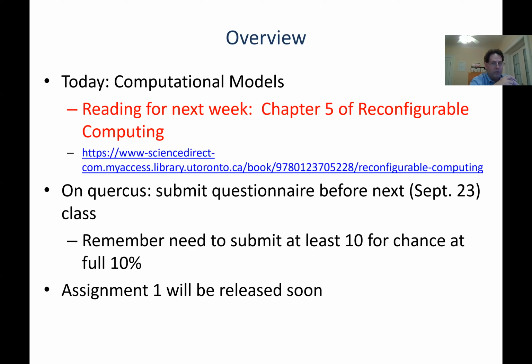You'll be given about 3 weeks to work on it, and it has a significant embedded tutorial. I'm not assuming that you are familiar with the CAD tools that we're going to use, which are Quartus and ModelSim, so a part of this assignment is to get familiar with those CAD tools. It does assume that you know basic HDL design, and it's easier to do in Verilog because the test benches we're giving you are in Verilog. But we don't assume an extremely deep level of HDL knowledge. If you're a bit behind on HDL, I'll post a couple of resources of where you could go to get up to speed. It is possible to learn what you need as you go along if you aren't that familiar with HDLs.